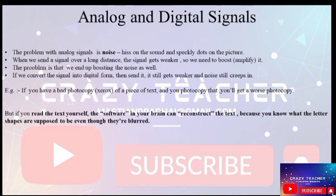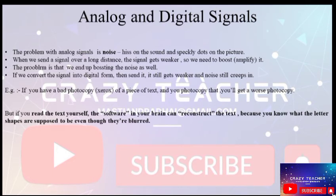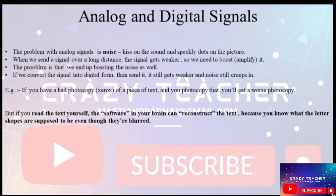Normally we put some periodic amplifiers on the path, and the amplifier boosts up the signal, so that at the receiving end you get a reasonably correct signal. The problem is that we end up boosting the noise as well. If we have a boosting station, and in the previous segment some noise got introduced, that noise will also get boosted up in the process. So that is the problem with the analog signal.